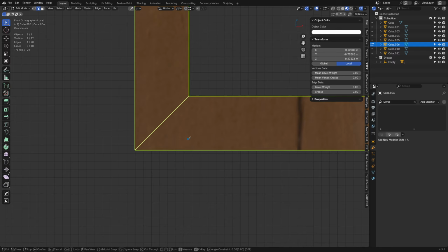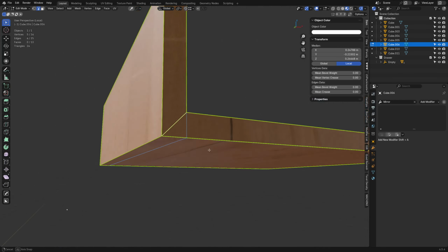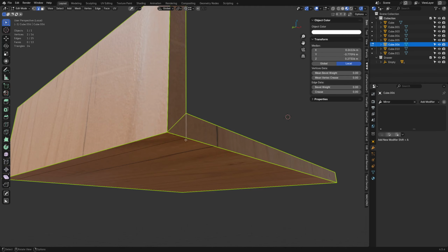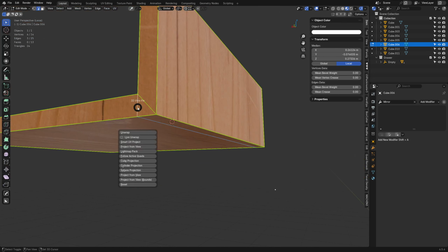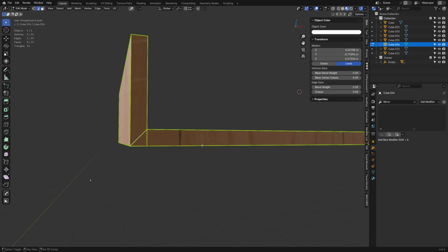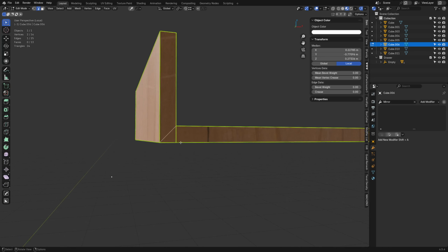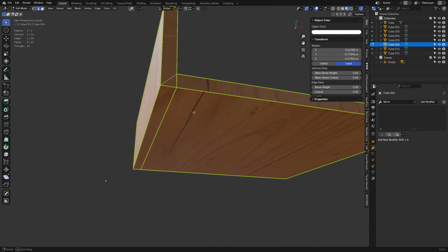So I'm going to press K, C, grab that vertex and hit Z. You can use X, Y, and Z as well with the knife tool. And I'm going to hit space bar. We're going to get this result here. Okay. So I want this texture to kind of run down to this corner in a specific way. So you need an extra seam to support that. All right. And we won't use this one here for that. All right. That adds an additional triangle. It may be something you want to do or may not want to do. It's okay. I think we'll be fine with it.